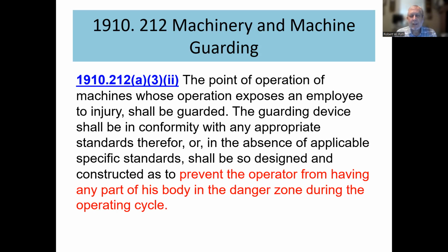Now you see they're getting back to this punch press mentality, the cycle. So boom, and it's cycles. And that doesn't always happen in a lot of equipment. It runs all the time, but that's that mentality when they did this guarding thing. They were really worried about this with good reason. And so they're saying here, if there's not a specific standard, it's got to be designed to prevent the operator from having any part of his body in the danger zone during the operating cycle. So this is one of OSHA's ways to prevent people from getting around the law.